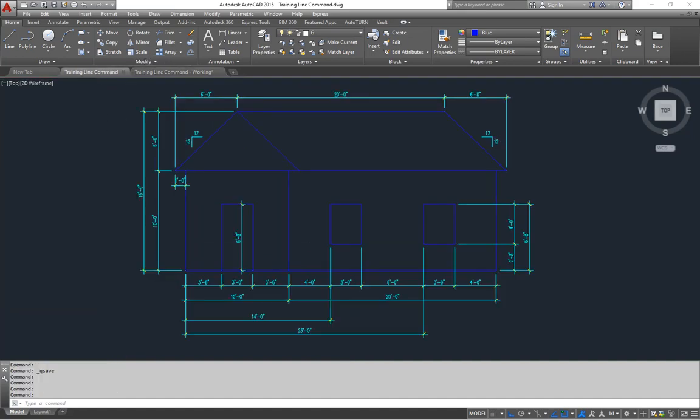Okay, now let's draw one of these openings, assuming they're like windows or something. As you can see, they're 3 feet wide and they are 4 feet tall. Now they are going to line up with the door opening, so this is going to be at 6'8" at the top of it. So let's just use absolute coordinates and start at this top corner of this window right here.